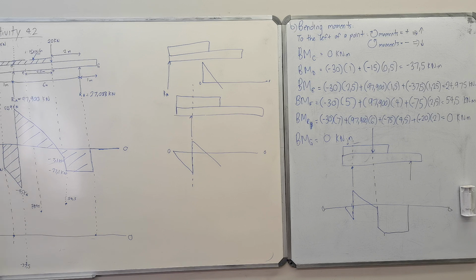If you look at page 76 at the bottom, bending moment diagram, concentrated load, can you see a loading diagram? You have an upwards force, one downwards force, one upwards force. Can we all agree that that's 3 concentrated loads? 2 concentrated loads pushing up, 1 concentrated load pushing down. So on a bending moment diagram, you would have a straight line between concentrated loads.